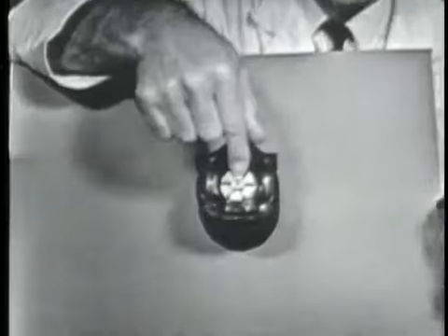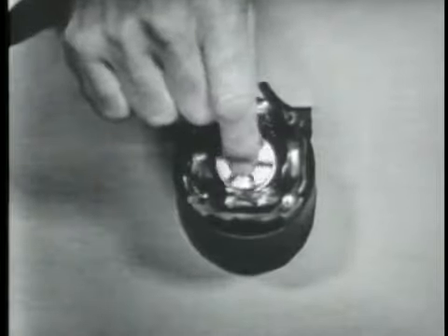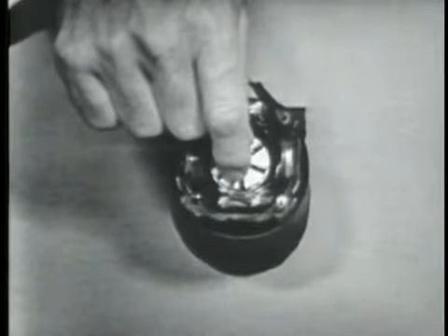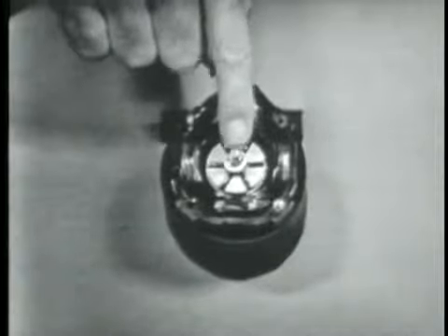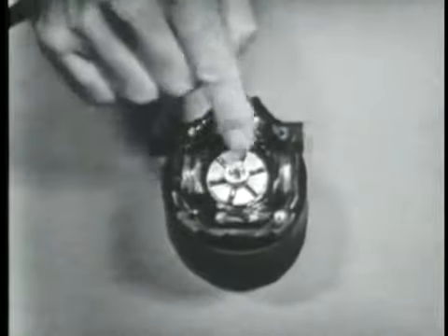Now, that depends on two things: the amount of internal loading and the amount of external loading. Now, what do we mean by that? Internal loading refers to the drag or the load on the motor caused by weight and friction. You mean like it would be easier for a little guy like me to push a small light car than it would to push a big old heavy clunker like yours? It'd be easier for anybody, Tom. Especially me. Right. The same thing is true of this rotor. That is, it takes a certain amount of energy to overcome its weight to cause this hunk of iron to turn. And, of course, the friction of the rotor shaft on the bearings adds to the internal load.